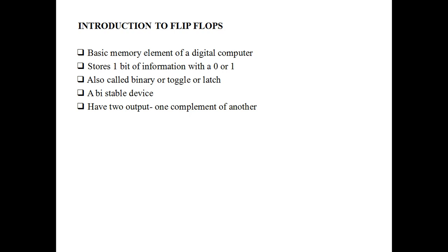Flip-flop is a memory element that is capable of storing one bit of information. It is also called a bistable multivibrator since it has two stable states, either 0 or 1. Flip-flops have two stable conditions and can be switched from one to the other by appropriate inputs. These stable conditions are usually called the states of the circuit. They are high, that is 1, or low, that is 0.